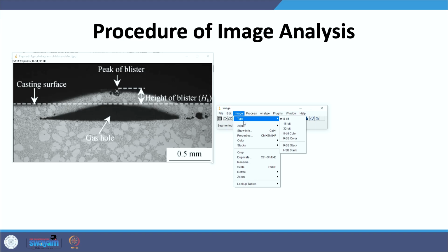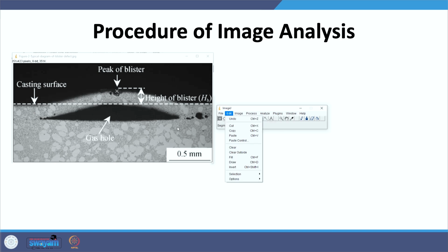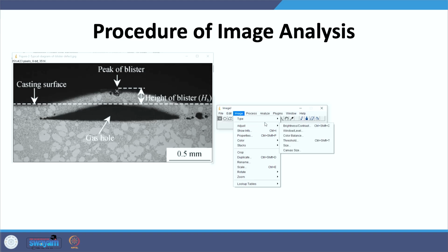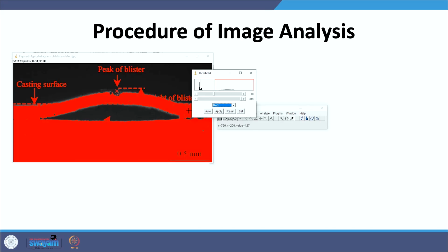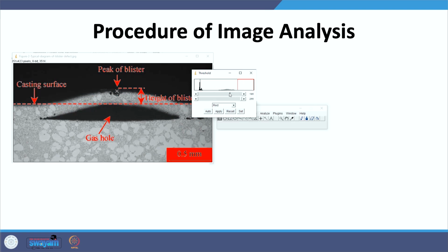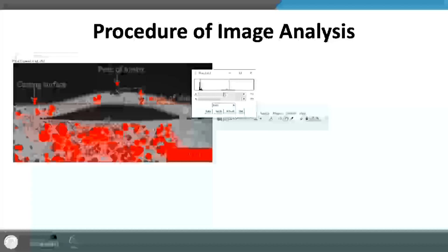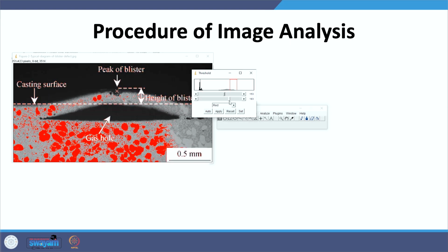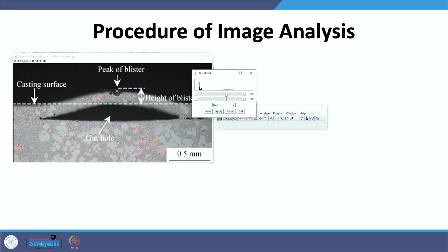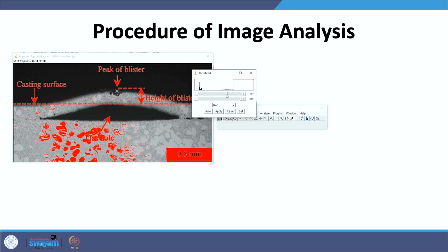And then now we'll adjust the threshold of the image. So, this is the threshold, and it will be adjusted. It is showing everything dark. There are two slide bars, and these will be adjusted as per the kind of phase or the area to be analyzed. We can continue to do this adjustment until we find that the desired phases to be analyzed have been selected. Say there is no phase selected, and now you see the alpha aluminum is getting selected like this.